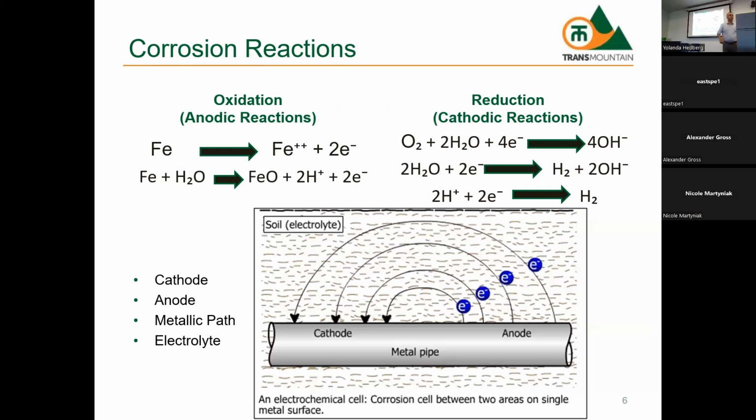Because we have OH minus hydroxide. Right. That's right. So as part of the cathodic chemical reaction on the surface in the environment that is corrosive, we are creating hydroxyl ions. Okay. We are altering the pH in direct contact with the metal. And that is what is protecting the steel.